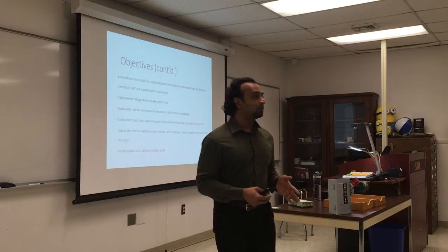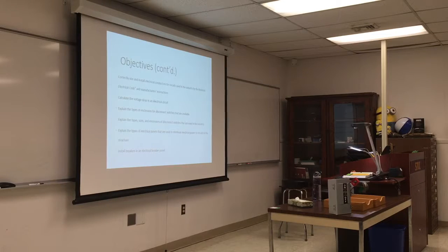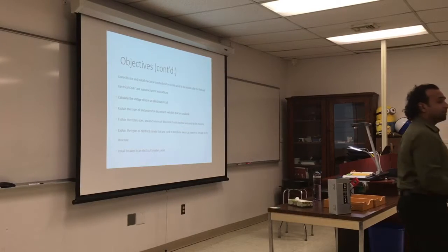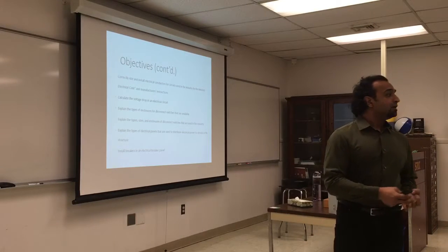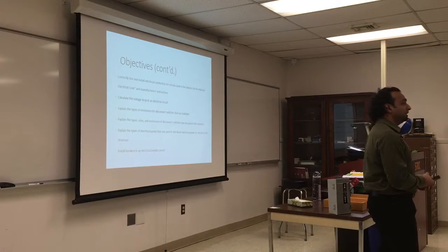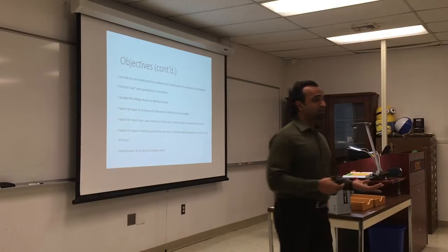What else do we have for enclosures for wire, like conduits? What kind of conduits do we have? This is some type of a conduit. There are wires going through it. There are plastic, there are sheathed ones, there are weatherproof, there are also the metallic ones, so we need to use the appropriate ones for each application, otherwise the wires are not protected.